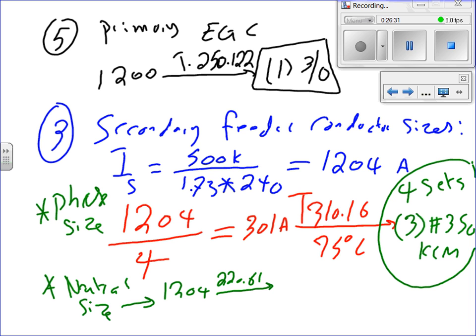220.61. Okay, the first 200, leave them alone. Anything higher than 200 is what? 1000. What do you do with them? Multiply them by 0.7 and get me the answer, will you? That would be something like 700. No, not even close. So the first 200, leave it alone. Anything else? How much? 903. Any gentlemen disagree? Dare to disagree with my friend Spencer? No? 903 amps.